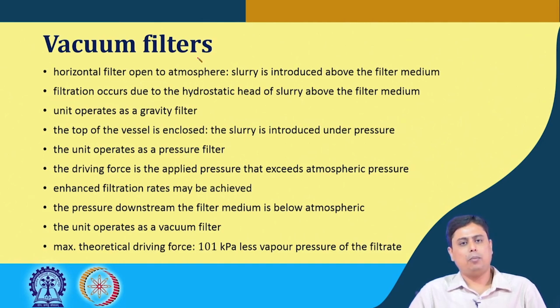Now, the filtration rate exists as long as this hydrostatic head is maintained, a certain hydrostatic head to overcome the resistance of the filter and the cake. So that means this kind of filter operates as a gravity filter.